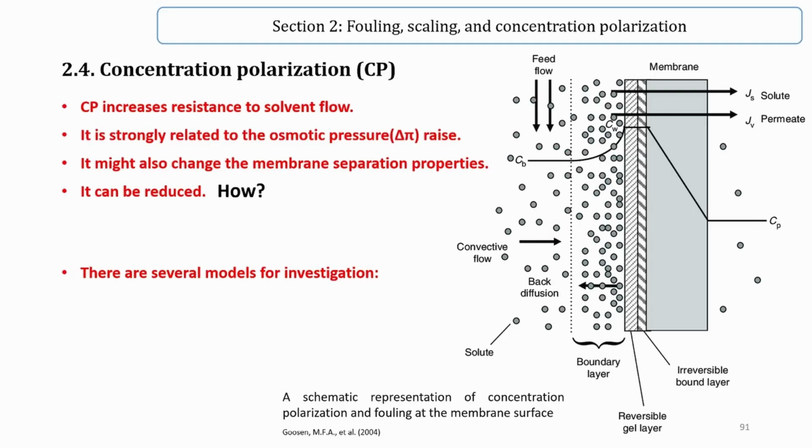Concentration polarization. The pressure-driven fluid flow through a selective membrane can effectively transport solute towards the membrane surface. The partially or totally retained solutes will accumulate in a thin layer adjacent to the membrane surface, generating a concentration gradient, that is to say, the solute concentration near the membrane surface is much higher than that of the bulk feed solution. As a consequence, a diffusive flux of solute back to the feed bulk appears.